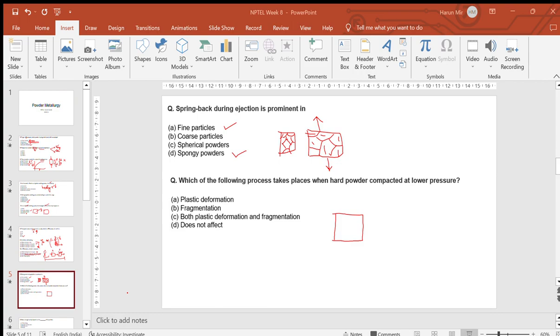Yes, I think two and elastomer. Yes, two and elastomer. So actually we have two types. Can you name the two types that we have for cold isostatic pressing? Dry bag and wet bag. Right. So we have two pressings, dry and wet.